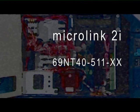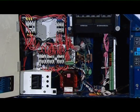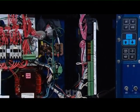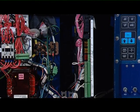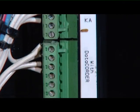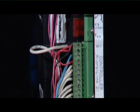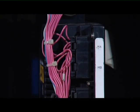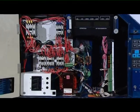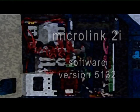Microlink 2i units are the 69N240-511 and the 69N240-521 models. These models have only one component, which includes both the controller and the data recorder. The Microlink 2i controller can be mounted onto the Microlink 2 units with the correct operational software. However, the Microlink 2 controller cannot be mounted onto the Microlink 2i units. The software program version for the Microlink 2i is number 5132.